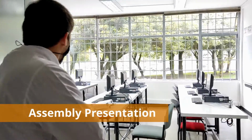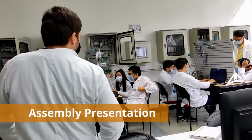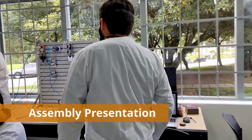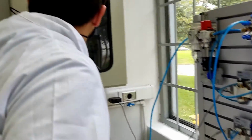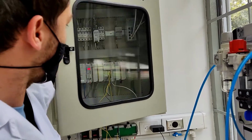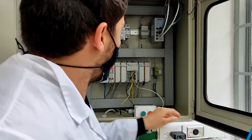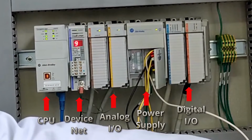To start, we are happy to share with you once again the facilities of our university and our workspace with the PLC, engines and pneumatic systems. In the automation lab, we can see a board with the power distribution and our PLC. In slot 0, we can appreciate the Allen Bradley PLC CPU CompactLogix L30ERM, which has the processor and memory. It stores and executes the program.